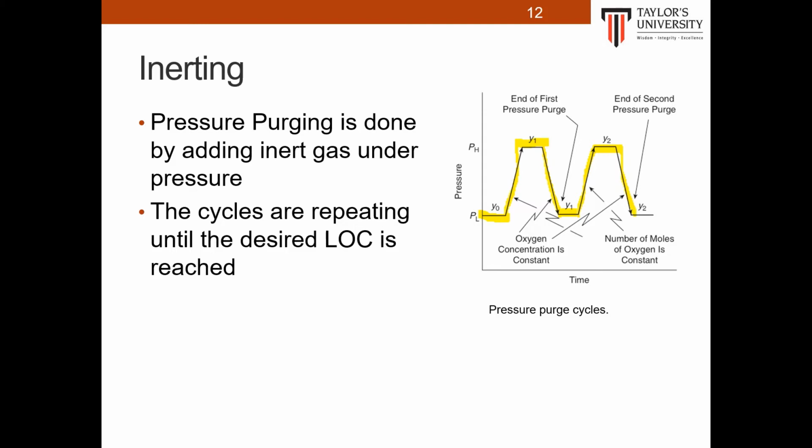So every cycle, the oxygen content is reduced because of the inert gas additions in the vessel itself. During the depressurization process, the composition of the gas within the vessel actually remains constant, but the total number of moles is reduced. So the oxygen mole fraction remains unchanged during these pressure release sessions. Okay? And we repeat these cycles until again the desired LOC is reached.